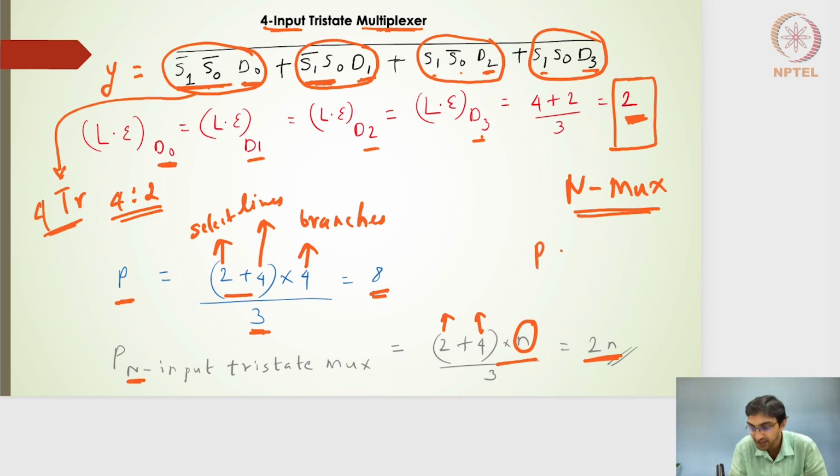So if I am having a delay P plus DH, this G value for an input doesn't change, whereas the P, of course, will change linearly with respect to the number of inputs. If I design it in another way, we will have a change in P, we'll also have a change in G. So in this particular case, when we have it branch-wise, based on the number of inputs, the G value doesn't change. Hope this is clear.